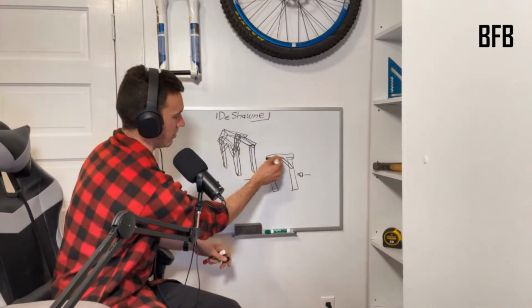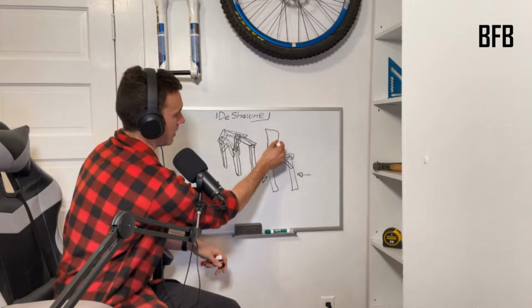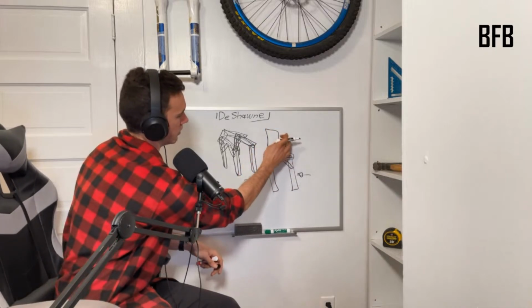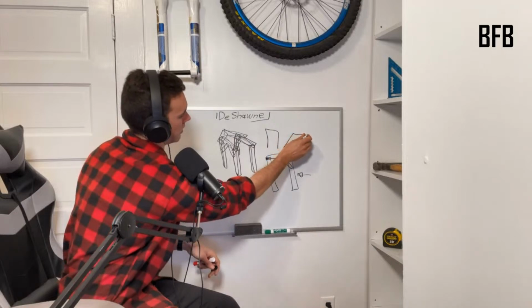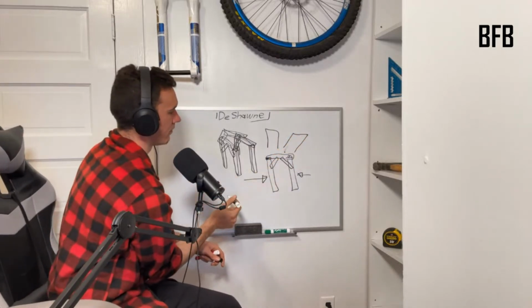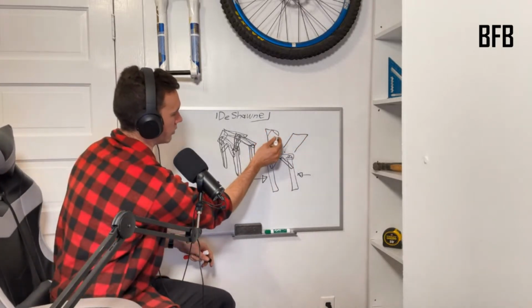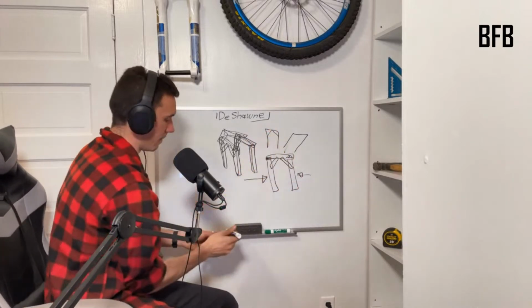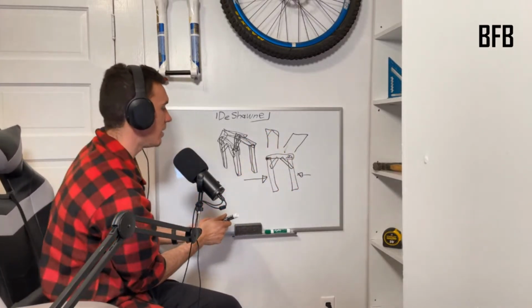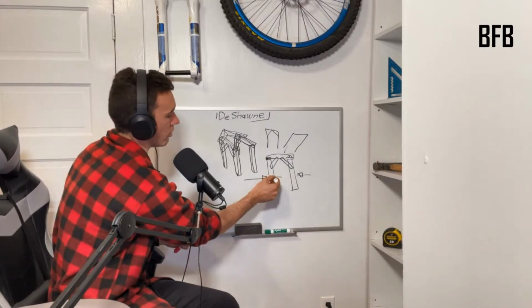Otherwise, you just have a hinge up here and a hinge up here, and the shape that looks like this can very easily, if you draw it correctly, could very easily look like that, and that'd be bad. But when you put in diagonals, what you've done is you create a little triangle that basically can't change shape and stiffens it up.